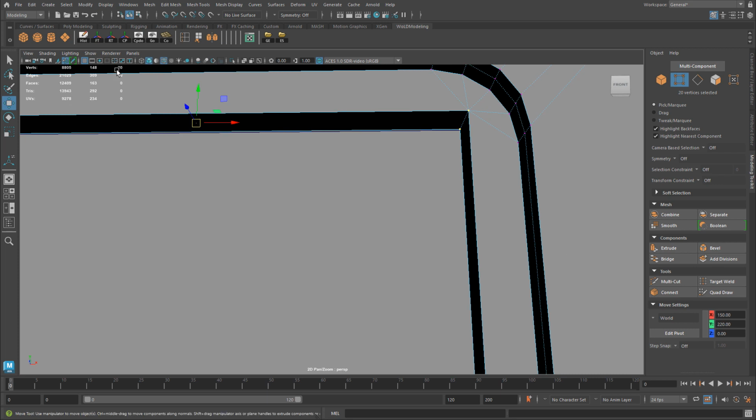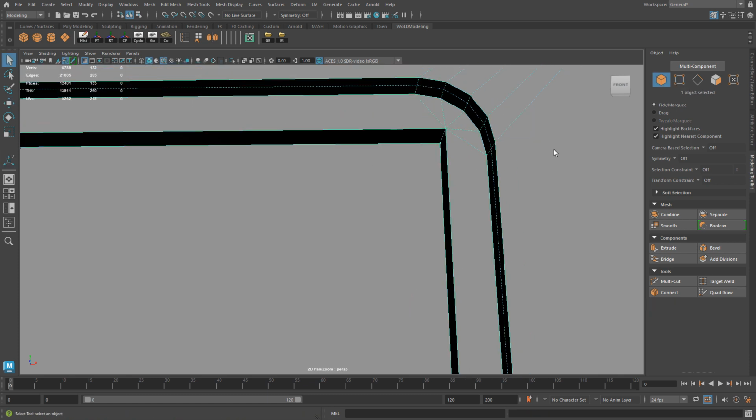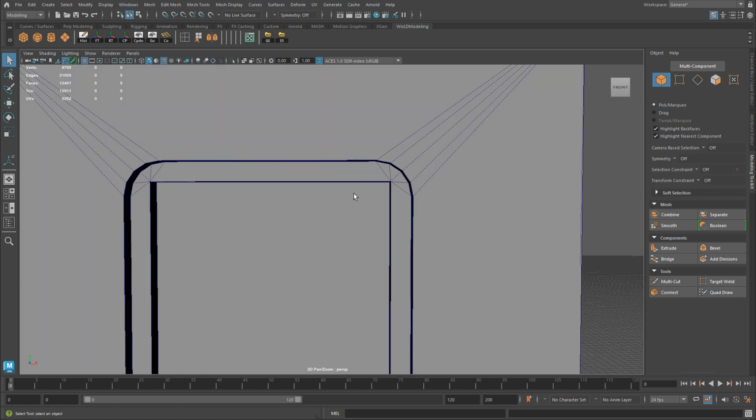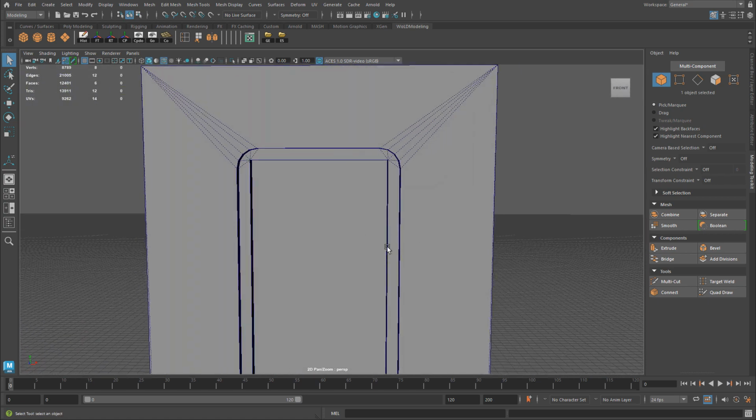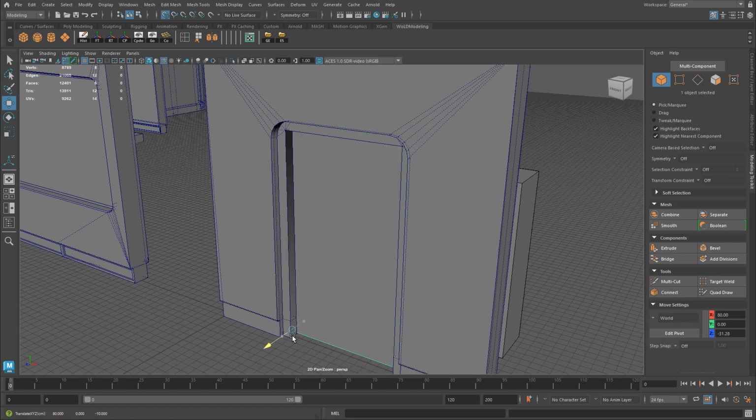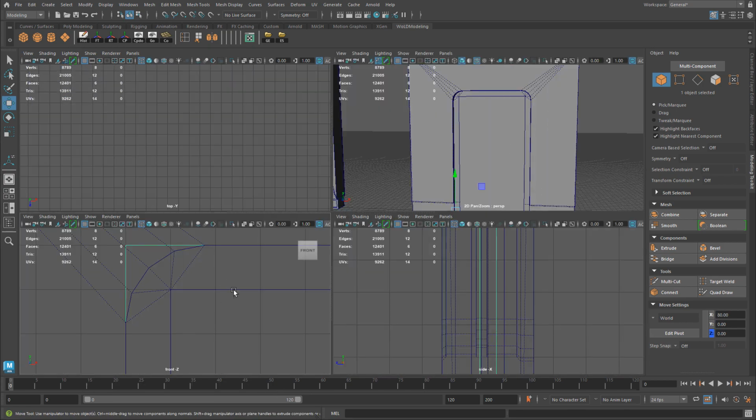At the moment I have 20, and I'm going to hold down shift, right click, hold, merge vertices, and it should bring me down to only 4. Perfect. Now they've been optimized. So that gives me a nice looking border and a door that I can position on top, right on the inside.